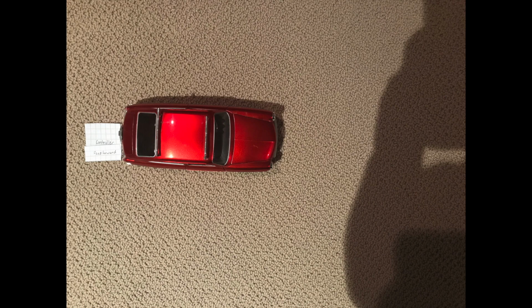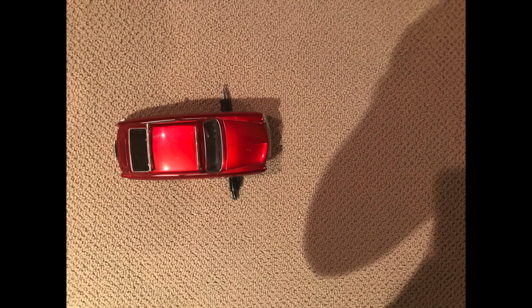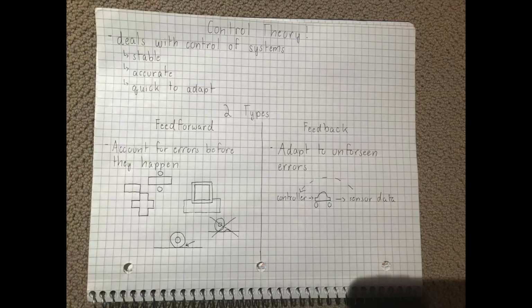Feed-forward control alone is pretty good when you're trying to make the car go at a constant speed along a constant surface, since that's something that can be easily modeled or calculated. However, when the car encounters something unexpected, like a bump, feedback control has to kick in. The sensor has, as usual, been sending data about the car's speed back to the controller.